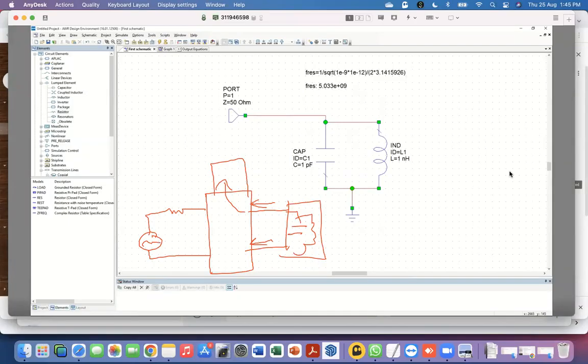To complete this answer, if you are talking about how we will do it in calculation, there you can just write down how you do it for, say, a quantum mechanical scattering problem. You write down the wave equations, and remember that at any point in space, the voltage is going to be the sum of the right going and left going voltage waves, right? So we will see these kinds of examples as we go on. By having enough equations and enough boundary conditions, you can separate these quantities out. And as I said, I will ask you to calculate these responses, the real, imaginary, and all of those quantities, for the simple case. So you will see how these calculations are done at that time. Is that clear?